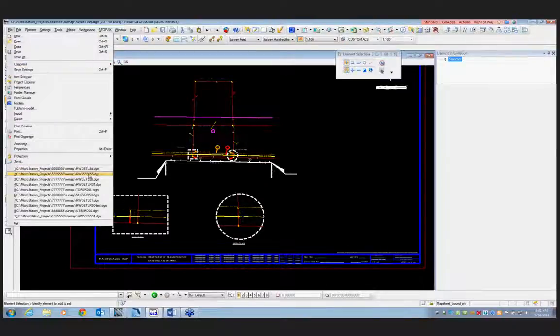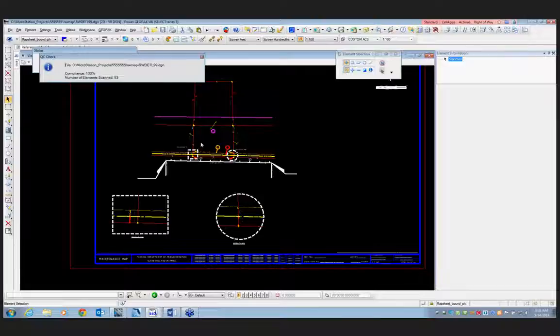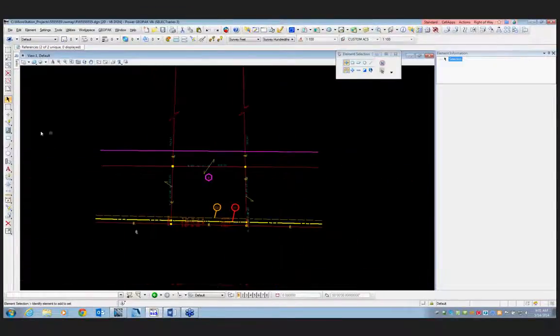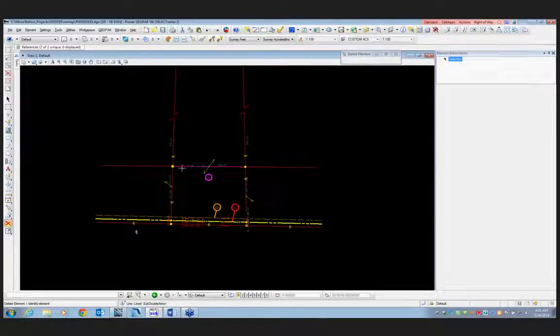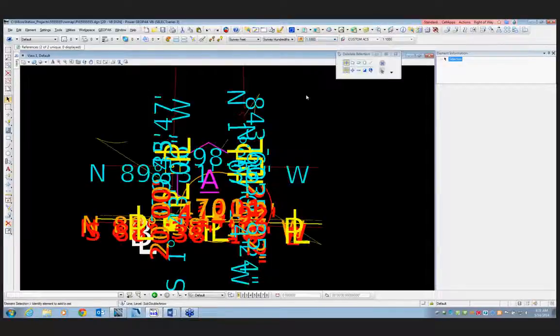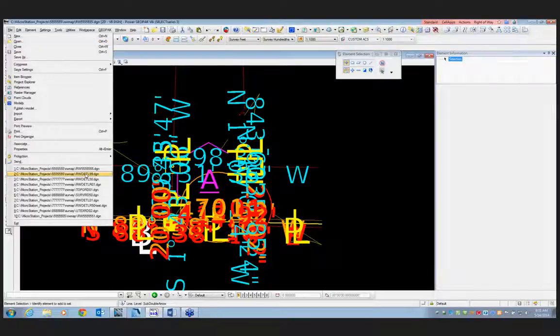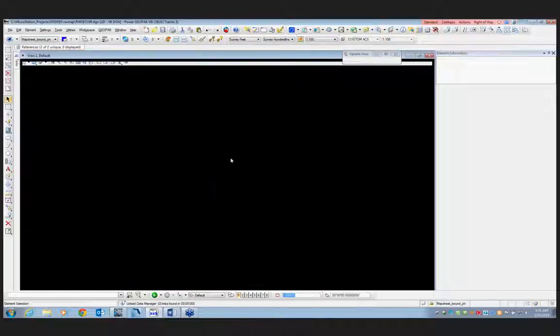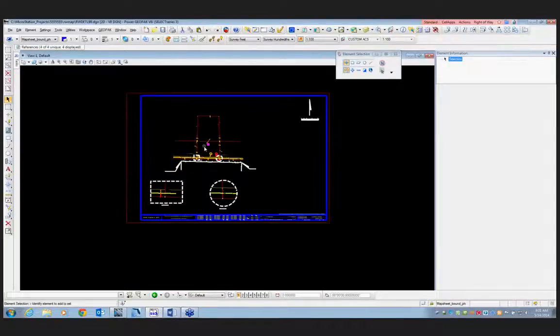We go back to the master right-of-way file here and I can delete something like this subdivision area. I'll delete it and show you. It'll be gone next time we look at the other sheet. But I can change these to any scale I want. I can set it to annotate, change it to 1,000 for instance. Go back to the sheet file that this is referenced into, and you see nothing has changed.